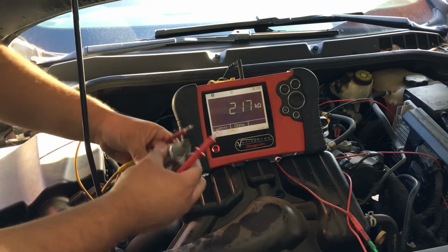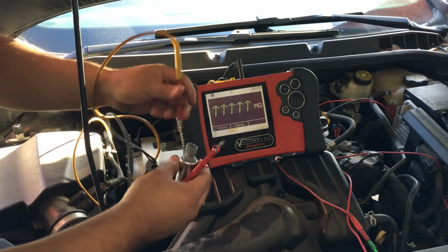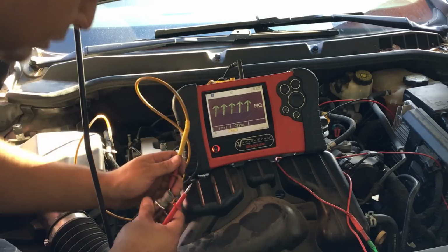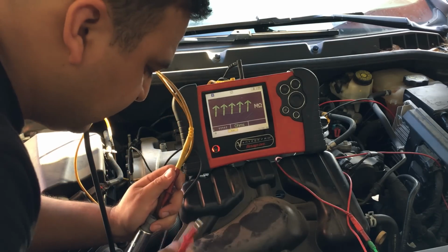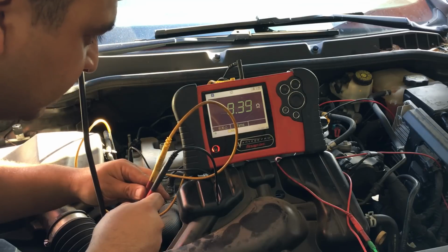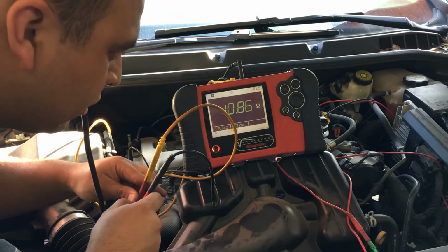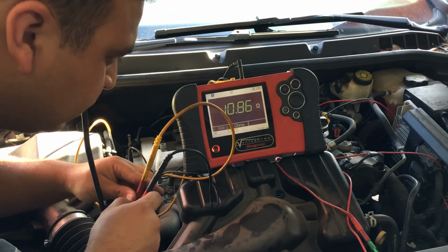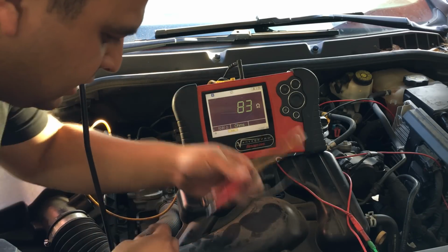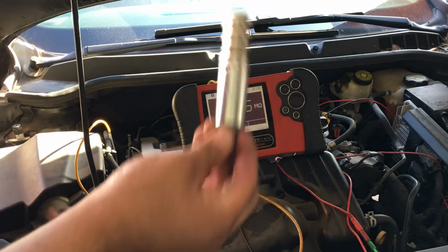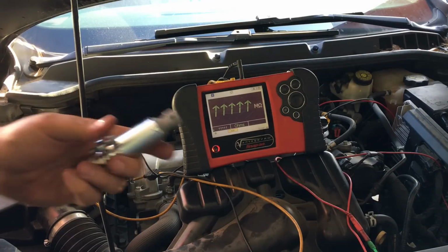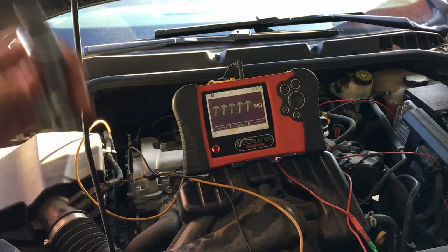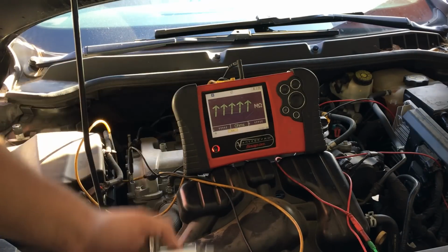I'm gonna go ahead and touch these 2 pins and see what reading we get. I'm touching both pins. Now if you look at the meter, we're reading about 10.8 ohms of resistance. This is on the brand new solenoid. So just for future reference, that's what the resistance is on a brand new solenoid. So if anybody's wondering what the specification should be and you can't find one, it's around 10.8 ohms.